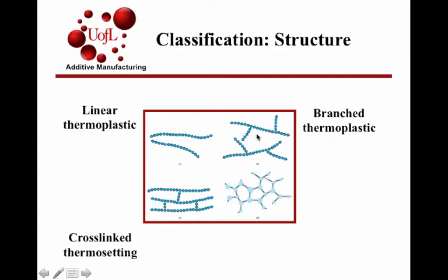If you react the material further, you could constrain the mobility of chains, with multiple linkages to other chains, and this is called cross-linking. And so you get a thermoset material. And if you have a lot of those cross-links generated through reactions, you have a net thermoset. These last two categories will be looked at in Module 2 when we look at reactive polymers. In Module 1, we'll look at these combinations.